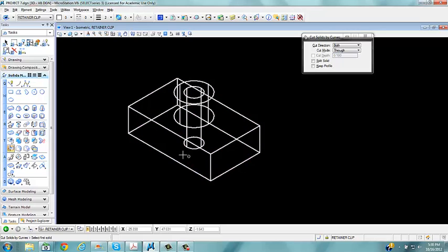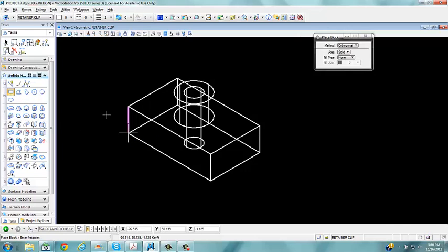We have a cutout in the bottom, and we're just going to do this with a shape. We'll use our W1 tool to place a block, and I'm just going to left and right mouse button on this bottom corner, hit O, and I'm going to hit S for side, and we're coming in 0.5 inches. Left click.